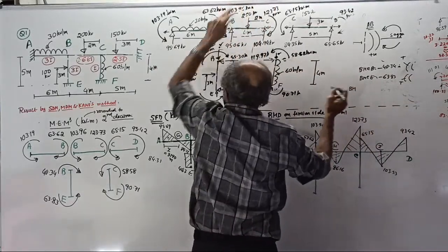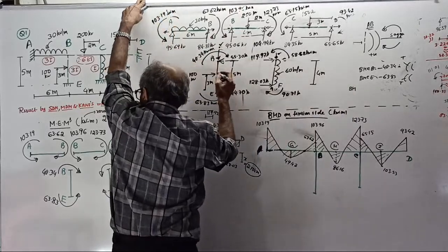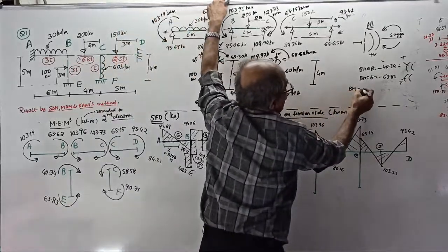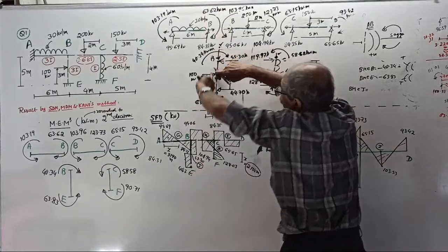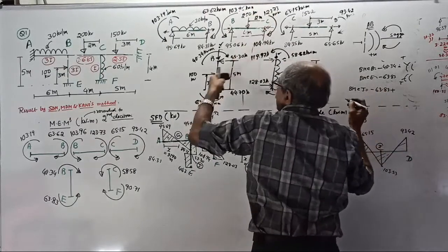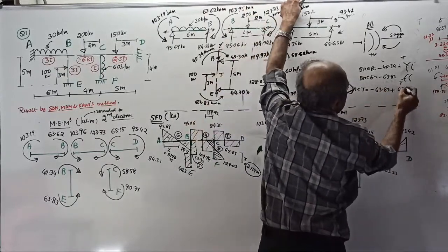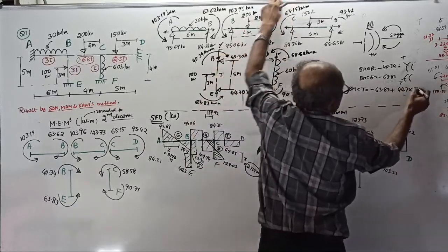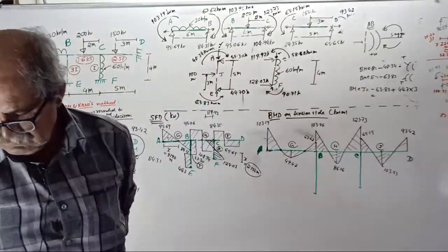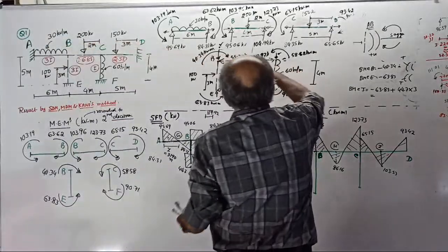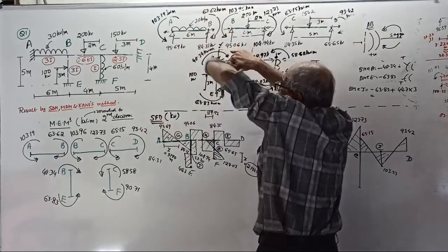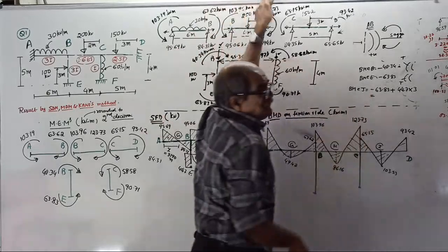Then bending moment at this point, what is the point called? That point you are calling as what? Name. J. This is called J. BM at J equal to, look this side, minus 63.83 plus 44.7 into 3. Tell the answer with sign. If I stand inside the beam, this is hogging, this is sagging. Hogging, sagging. Tell the answer with sign, fast.